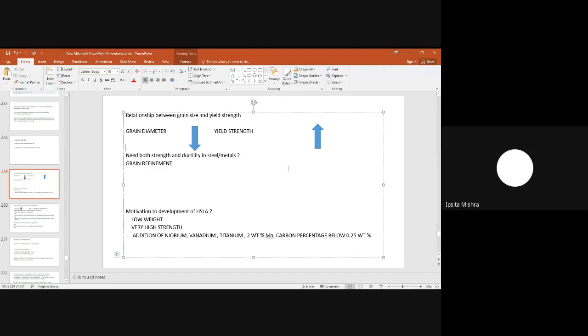Carbide. What carbide? Okay, Latmika, can you answer it briefly? I know you can answer it. Yes, sir. It prevents grain coarsening. Just elaborate the answer. At 1000 degrees centigrade, what phase will be there, and what will happen if these carbides or nitrides are there? Sir, at 1000 degrees Celsius, the phase will be austenite.